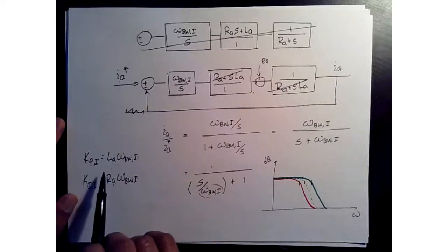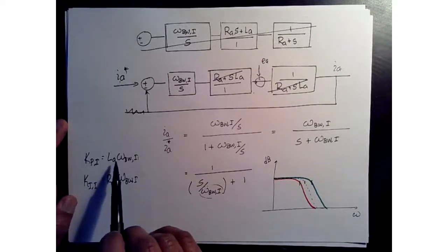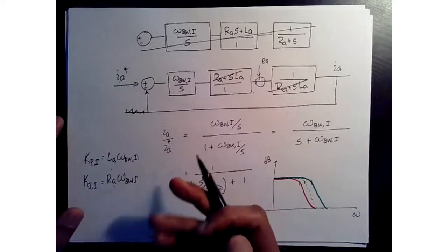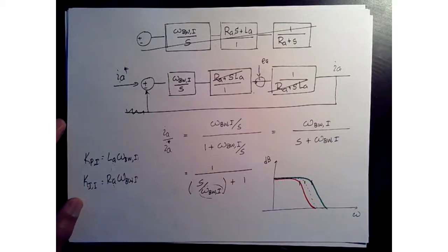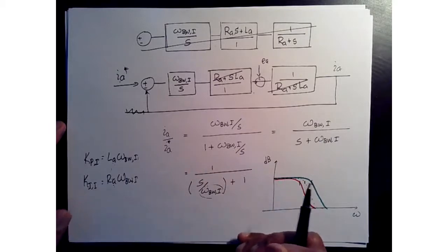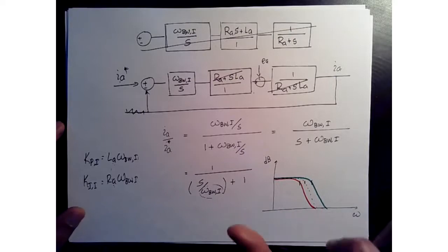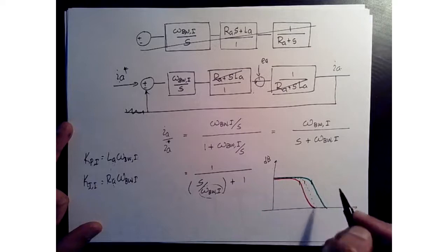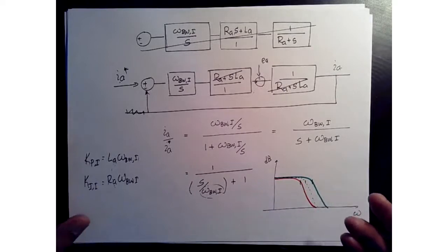Two, if for some reason your parameters change, or by mistake you use the wrong parameters, now you create a second order system. Okay, so that's something you have to be careful of, because second order systems have a resonance frequency.